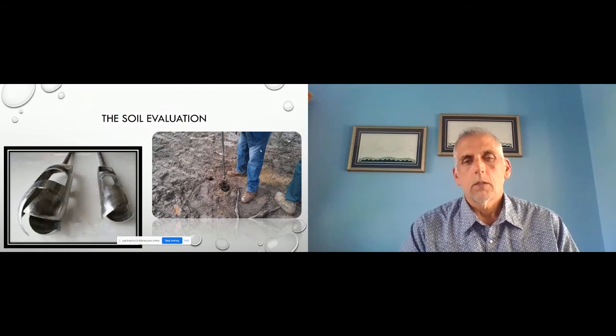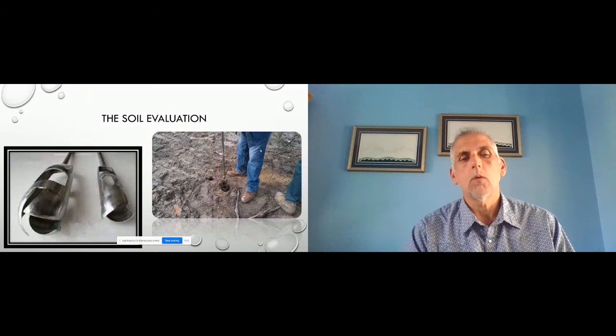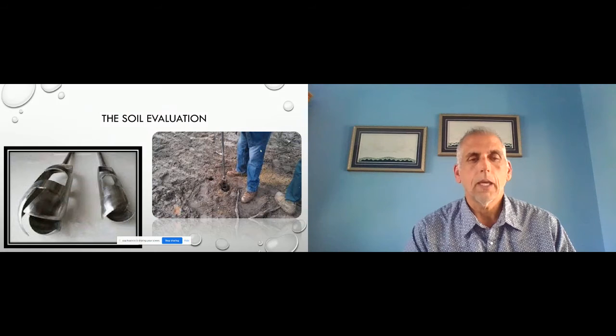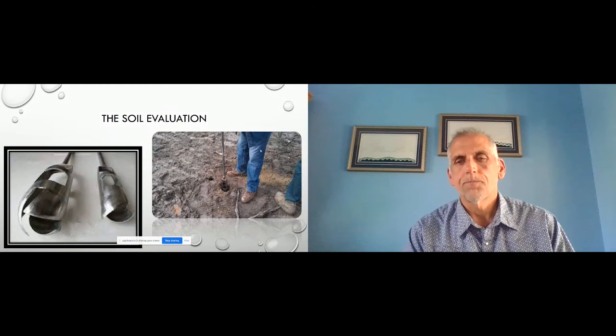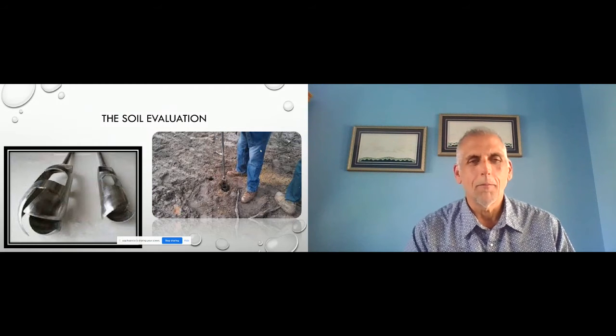Yes, we still have pit privies. We have pit privies for houses still. We do not have new permits for pit privies for houses, but we can still write a permit for a pit privy. It's still part of our rules that if a camp wanted a pit privy, then we could write a permit. But we have to evaluate it. We have to evaluate the soil. We have to look at if that soil is deep enough to put the pit privy on top of it. I'm sure when they first started, that wasn't done. Here's some guys that y'all may or may not be aware of. They're actually not those guys, but just having a little fun.